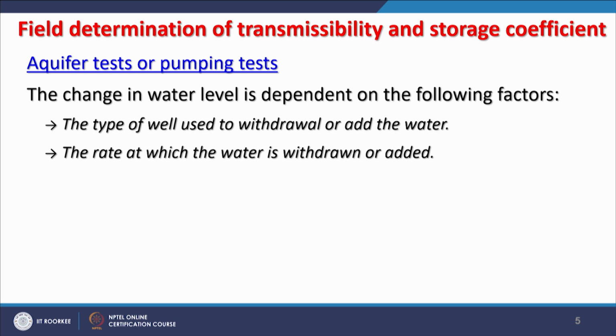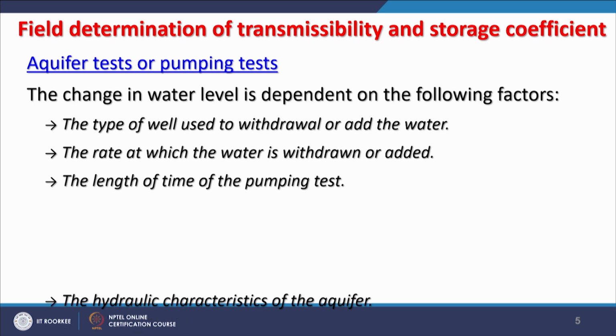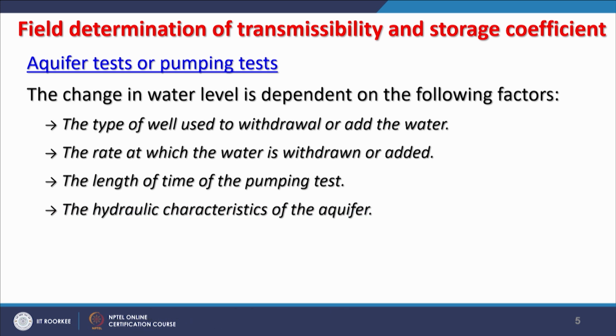And the rate at which the water is withdrawn or added. The water level will depend on this, that is, at what rate and how the pumping is being done. Then the length of time of the pumping test. During these pumping tests, the length of time may be, depending on the aquifer conditions, 24 hours or more, so that we get steady state conditions, if we are getting them at all. And then the hydraulic characteristics of the aquifer, that is basically our aim, but water level depends on all these factors.